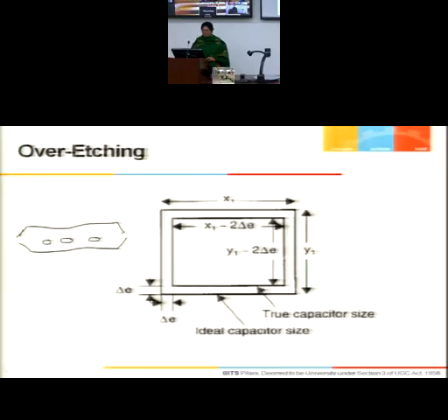As you are flowing the oxygen, maybe oxygen is made to flow from this way. So rate of reaction would be higher here, it would be slower here. This gas would be laden with oxygen molecules. Concentration would be much higher than the concentration at the rear end of the furnace. So rate of reaction is going to be higher at this end and slower at this end. So T-ox growth would be more here in the same time than the T-ox growth here.